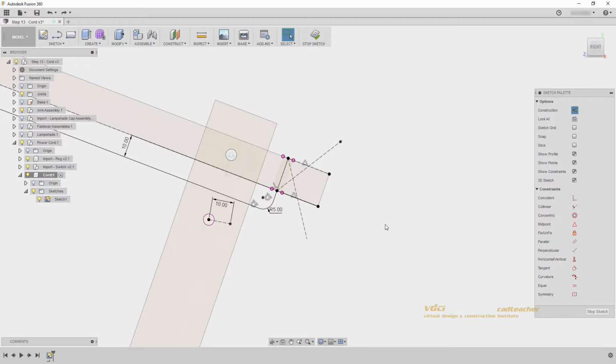Again, these are advanced sketching techniques, and you probably will never have to use them in a project. But I would like to show you how to exactly snap in a spline for parametric design. So now let's add our spline. I will uncheck Construction Geometry toggle, and let's go Sketch, Spline. I will click once, twice, third time here, and fourth time there, and then I'll hit the check mark.